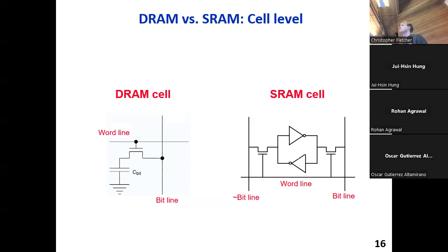Furthermore, because of this self-restoring system, reads are not destructive. So in an SRAM, if you read a value, you need not write it back to restore it because you're not dumping charge out from a bucket onto the bit lines. You're just turning on the faucet and connecting the faucet to the bit lines. And once you disconnect it by turning off the access transistors, that's perfectly fine. The faucet still keeps on flowing. Don't need destructive reads. So no destructive reads, no refresh.